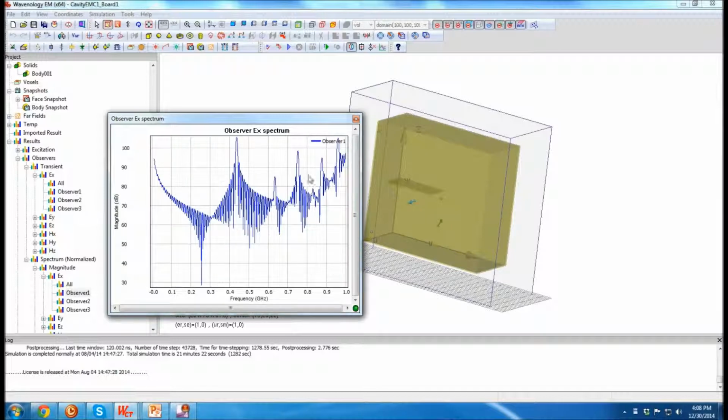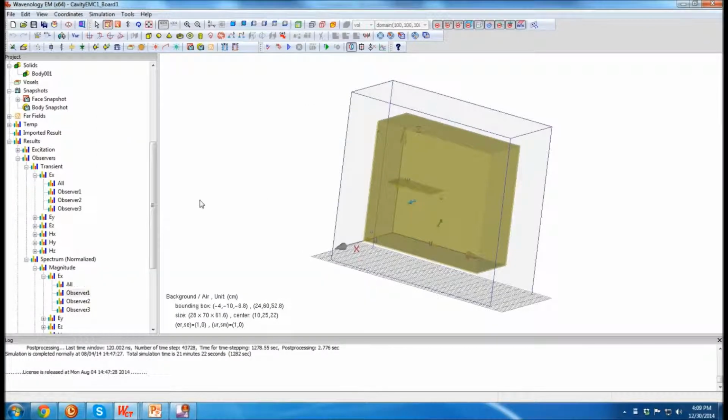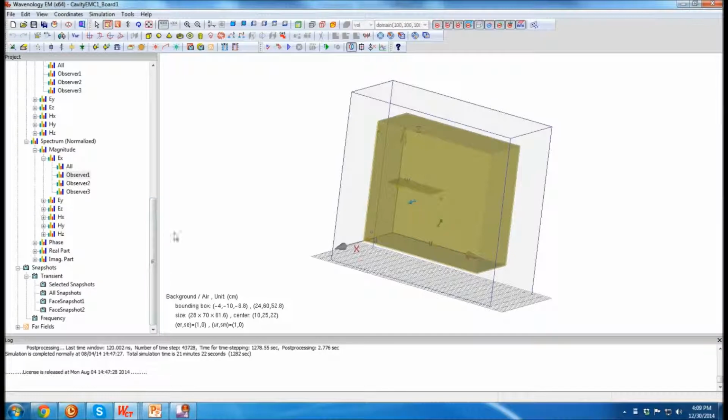But you do see that there's extra modes coming out due to introducing this new board inside this PC box. So that indicates, if you have a complicated internal structure of your PC box, you will have a lot of resonant modes that will be excited with some ESD signals or sparkling effects. Okay, so we got to be careful with that on the frequency changes.